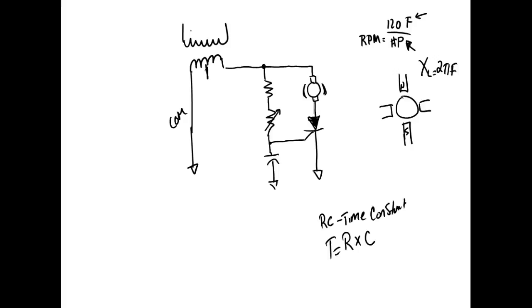Because a DC motor, we could control those with SCRs, right? Very, very easy. But electronics came out. Now we have variable speed drives. Now the advantage of AC motors, they're a lot cheaper per horsepower. And if you're going to control the speed of the motor, you're going to have a drive anyway. So this is why in our speed controls on new applications, AC motors are dominating now. But for years and years and years, we had DC motors, and they're still out there. And there are some applications you can't put AC motors in, right?